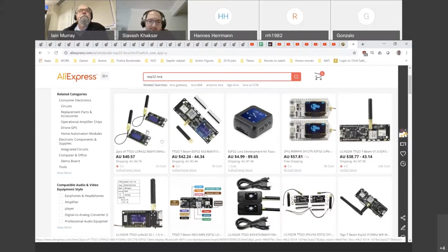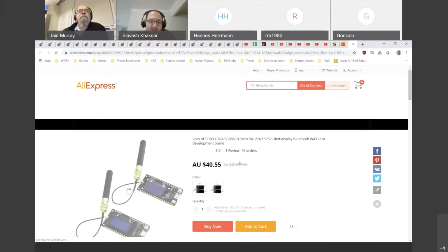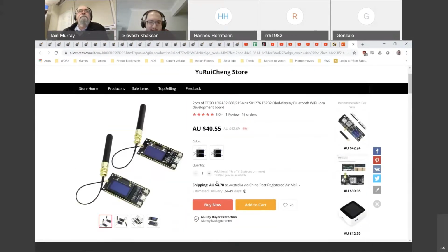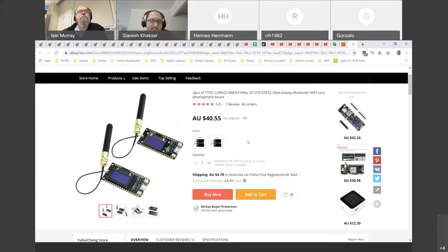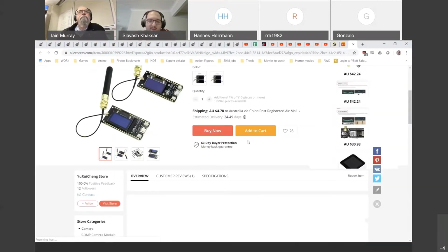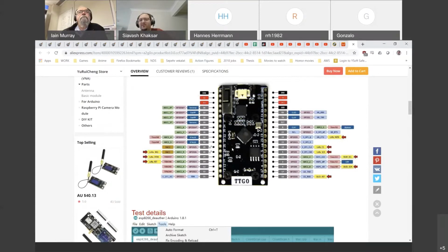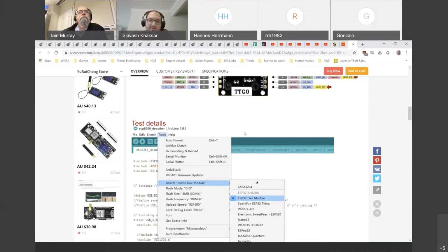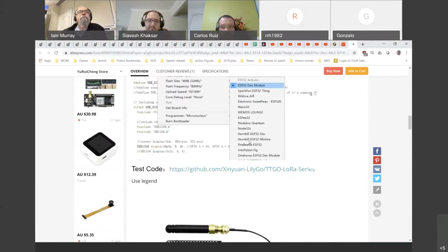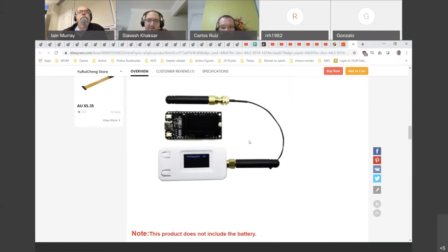They're very popular. They usually have an LCD there as well, and they're based on ESP32. They've become popular because they have a Wi-Fi and Bluetooth module embedded in the same micro. Even though it's not an Arduino, there's an Arduino core available for it, so you can just program it using Arduino. This could be a good option.